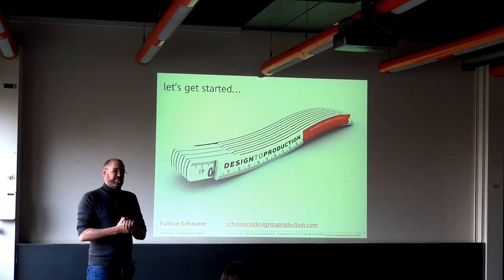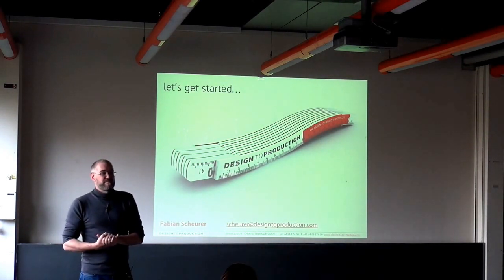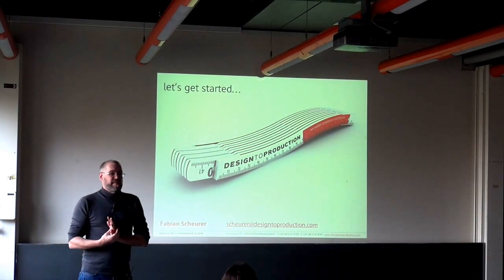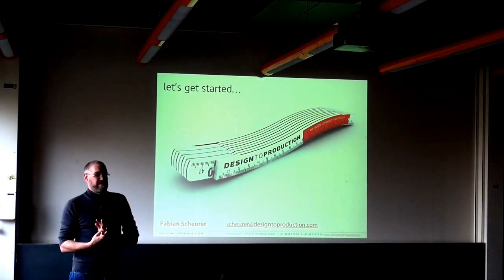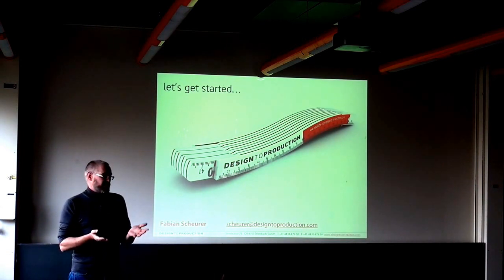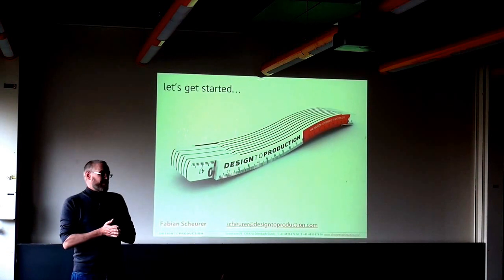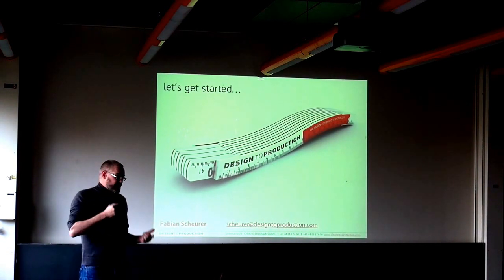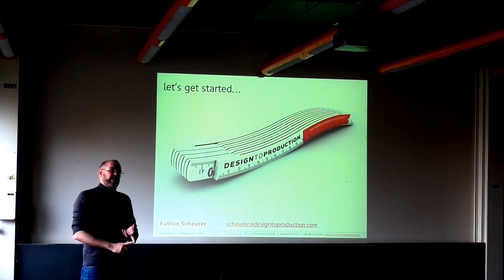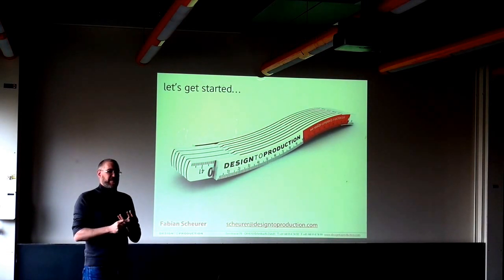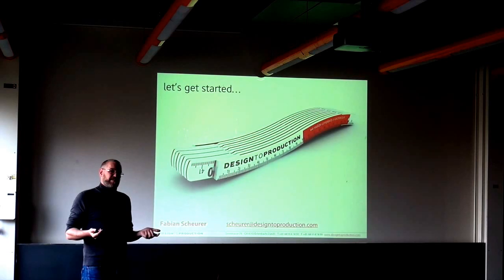I'm insisting on that point just to clarify maybe for the students that when you say 1 to 50, you talk about the amount of data that needs to be present. Yeah. So in the digital world, of course, there's no 1 to 50. A millimeter is a millimeter in the model basically. So it's 1 to 1 in terms of modeling scale, but it makes a huge difference in level of detail, and it makes a huge difference in modeling quality. The quality of the model, you simply don't care about 1 millimeter left or right if you're thinking in a 1 to 50 world, because it doesn't matter.